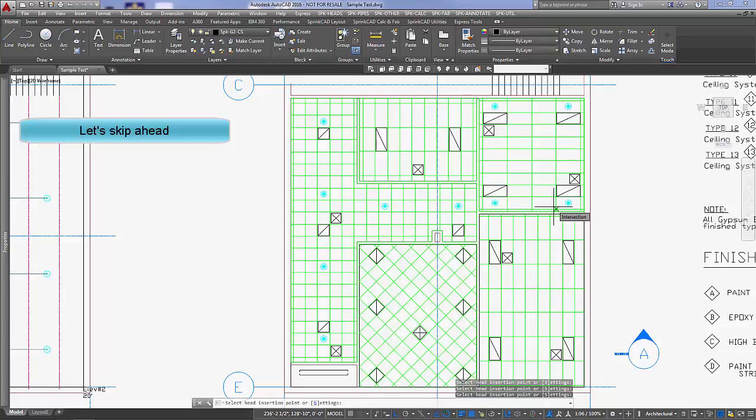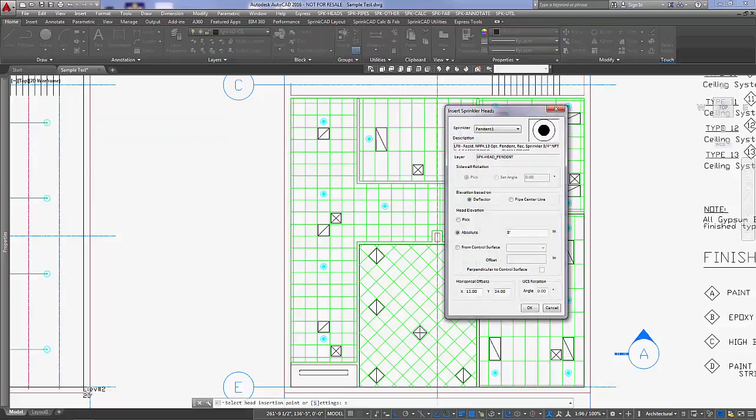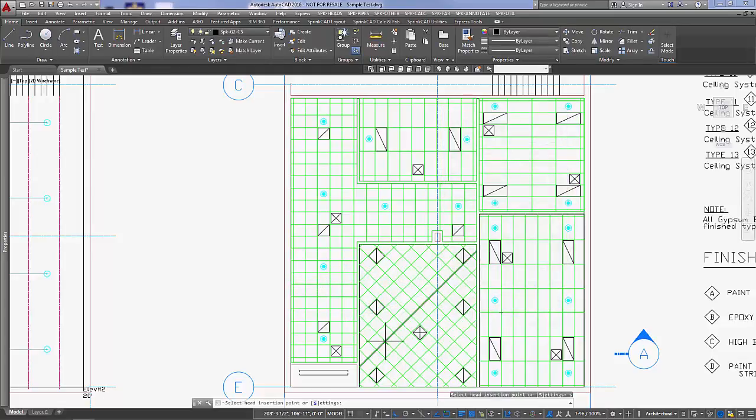and then we'll take a look at the room with ceiling tile at an angle. By changing the rotation along with the offsets, you can adjust for a rotated tile pattern. And based on the 2-foot square pattern, a 12 by 12 offset works here. And rather than having to do the math for the angular adjustment, you simply set the angle to match the tile. Now we'll see the office heads have been inserted at an elevation of 8 feet.